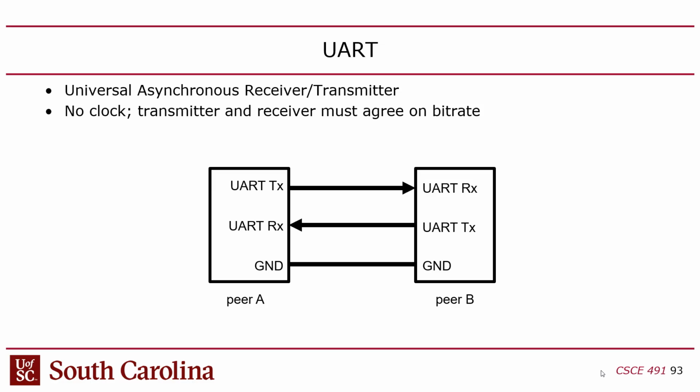And now there's lots of baud rates. You can go up to 115,000 baud. I've even seen the ESP32 upload at 900 something thousand. That's the biggest I've ever seen. But they can get insane nowadays. So it used to be pretty much 96 or 57. Now there's lots of options, and I never get it right. I never know what to set that baud rate to.